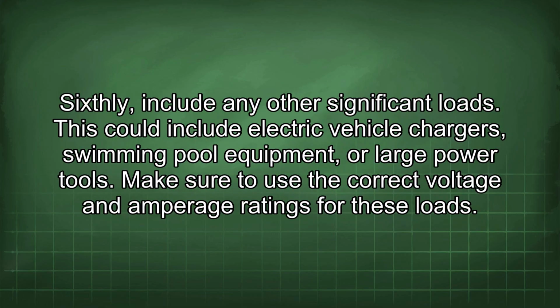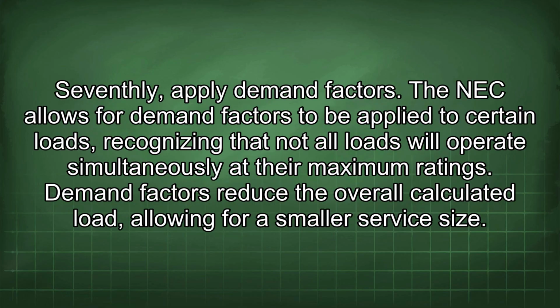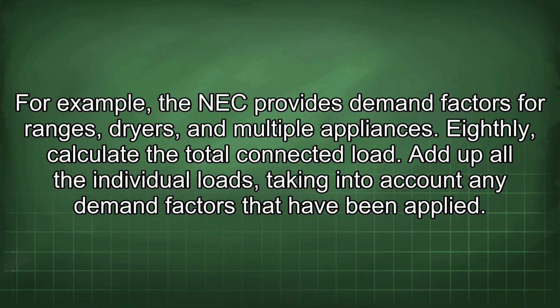Sixthly, include any other significant loads. This could include electric vehicle chargers, swimming pool equipment, or large power tools. Make sure to use the correct voltage and amperage ratings for these loads. Seventhly, apply demand factors. The NEC allows for demand factors to be applied to certain loads, recognizing that not all loads will operate simultaneously at their maximum ratings. Demand factors reduce the overall calculated load, allowing for a smaller service size. For example, the NEC provides demand factors for ranges, dryers, and multiple appliances.